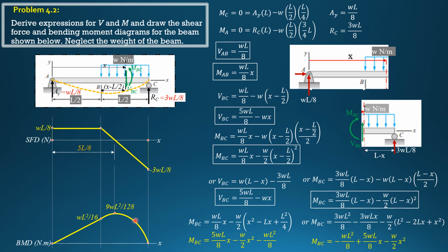How do I know that the curve is like that? You just set an intermediate value and it is concave down. You describe the ordinate of the shear diagram. The shear is 0, then the shear here is negative, so negative slope which is increasing like that. Or you substitute an intermediate value, let's say 3/4 of L, then you plot.